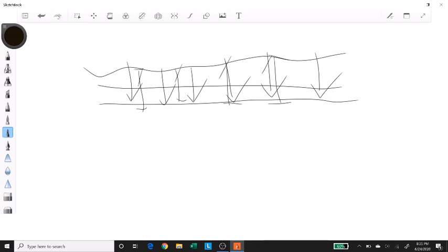So this was all about finding out relative height difference between 2 points. Usually we use a reference point whose elevation we set. So let's say I am doing a survey over here. I can select one point, which is usually the lowest one, and I can give it an elevation of 0.